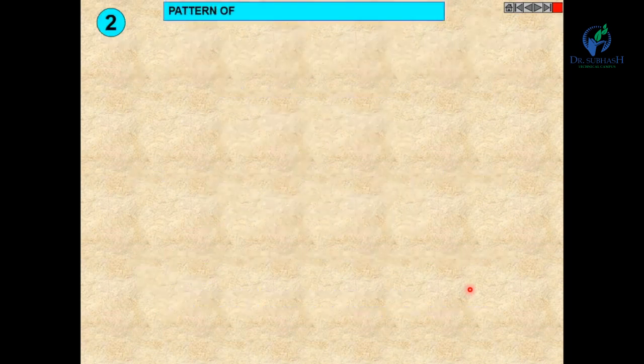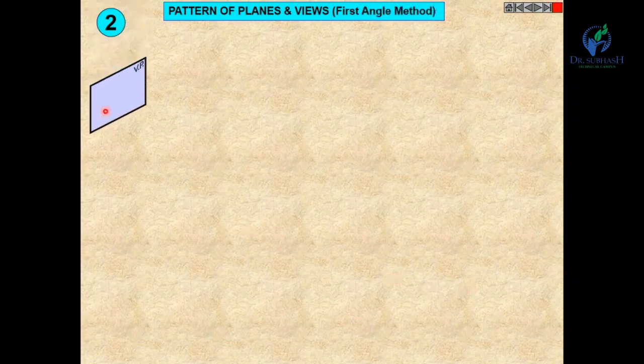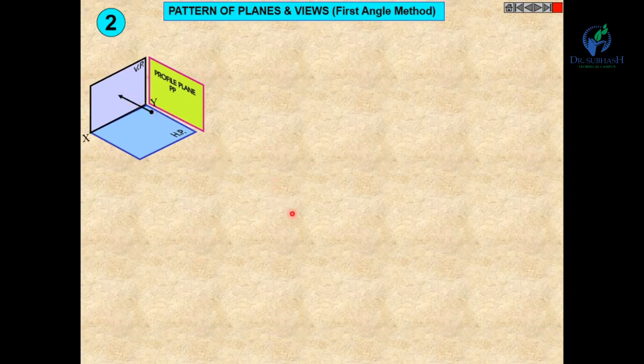Now let us see patterns of planes and views, first angle method. You can see this plane is known as the vertical plane, VP. This plane is the horizontal plane, and this plane is the profile plane. All the principal planes are perpendicular to each other. The intersection line between HP and VP is XY. This arrow shows the direction of the observer.